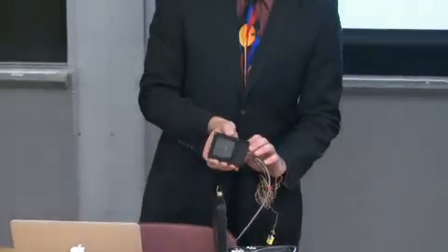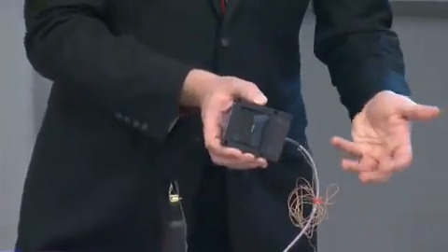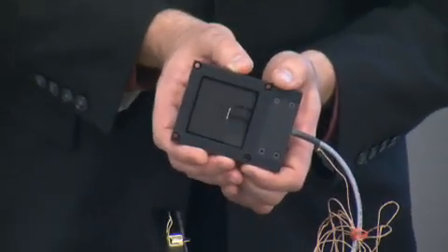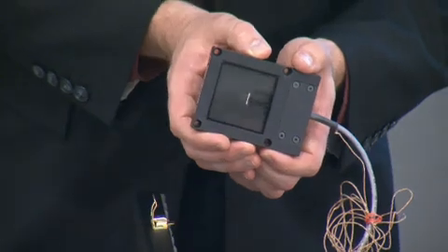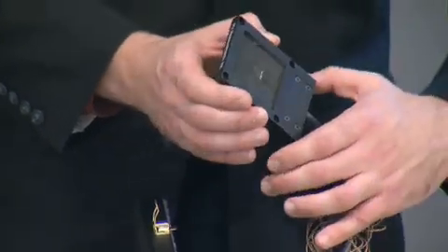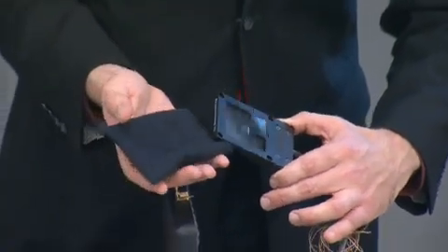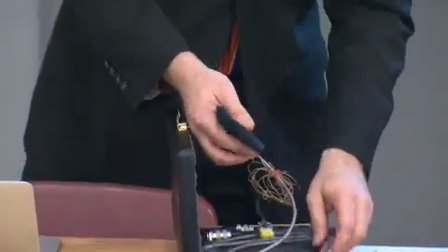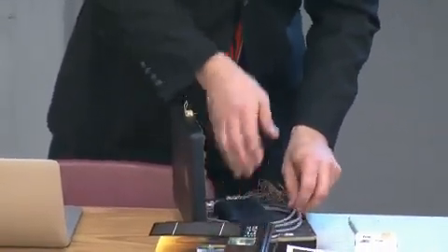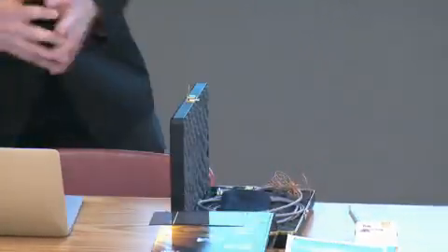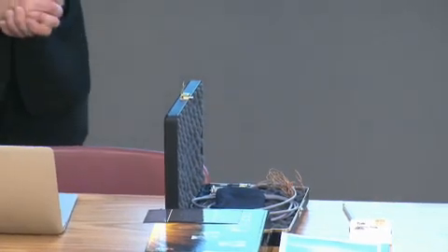So this is an example of a very small crystalline silicon solar cell device inside of an encapsulated frame. And the encapsulation is meant to prevent any degradation to the solar cell, as well as damage that might incur during accidental use. And this cell is called a reference cell. It was tested at NREL. The short circuit current, open circuit voltage, and fill factor of that device are well known and reported. And it is essentially sent with that device back to our laboratory.